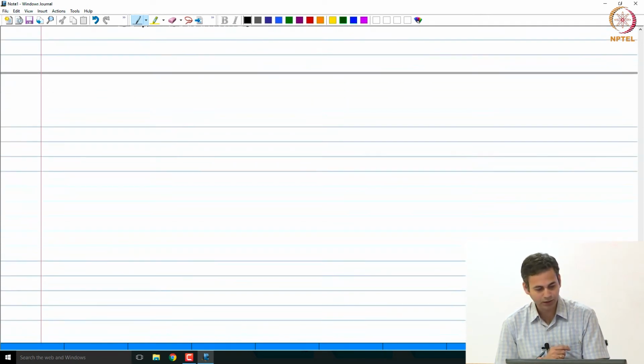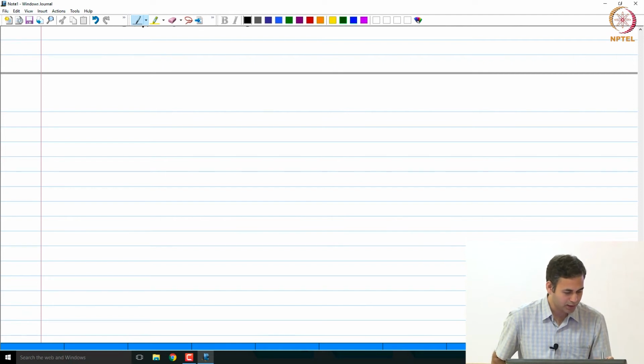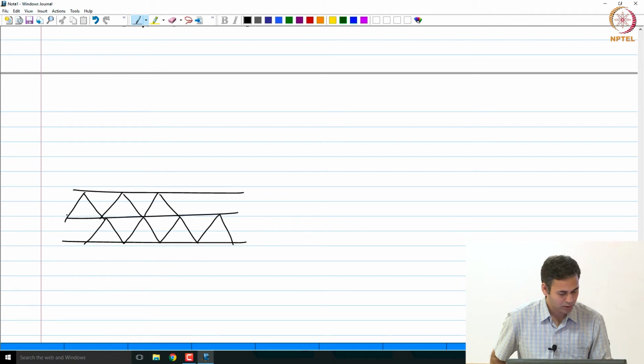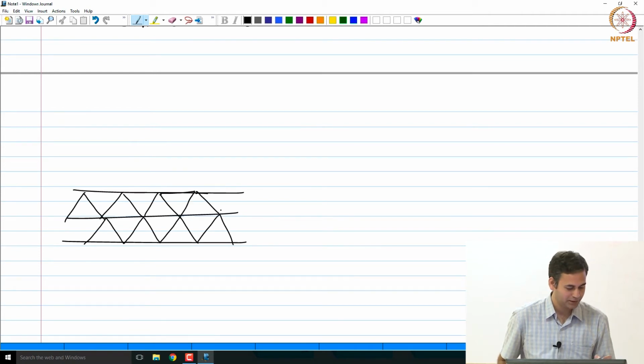Let me give you an example of how an orthogonal mesh looks like. Okay. So does it look like an orthogonal mesh? No? Yes? So essentially we have, let us say, equilateral triangles and the face normals are parallel to the line joining the cell centroids.